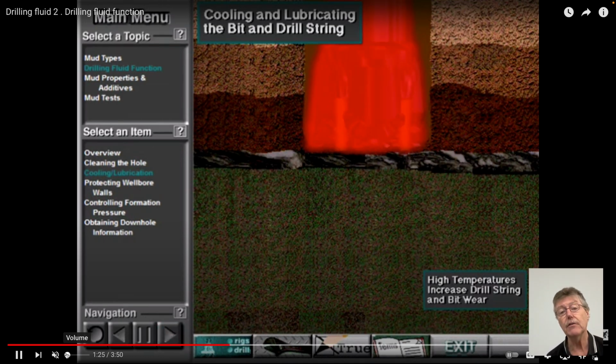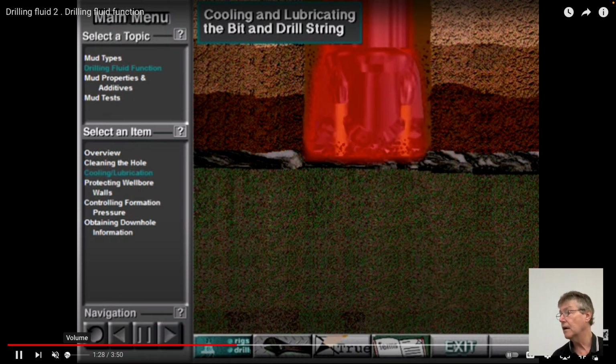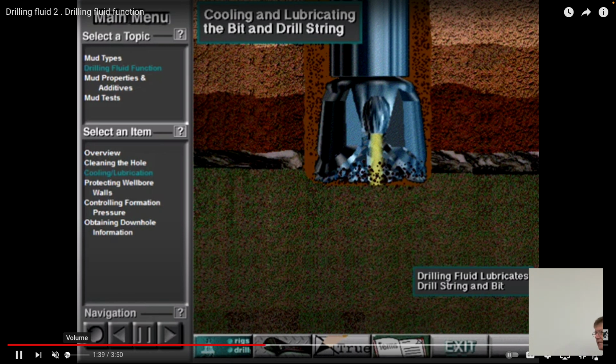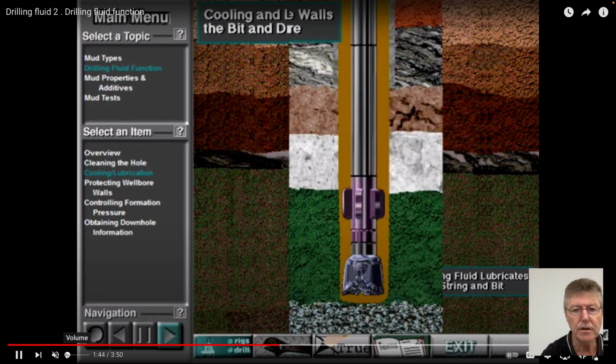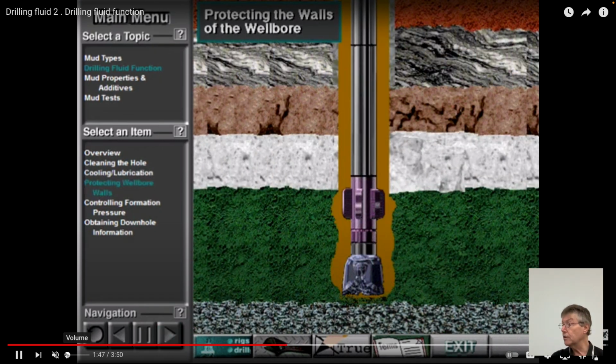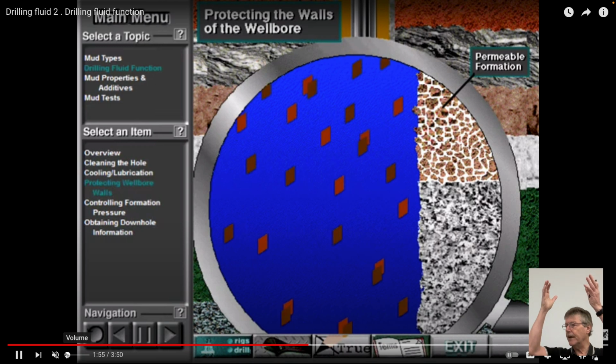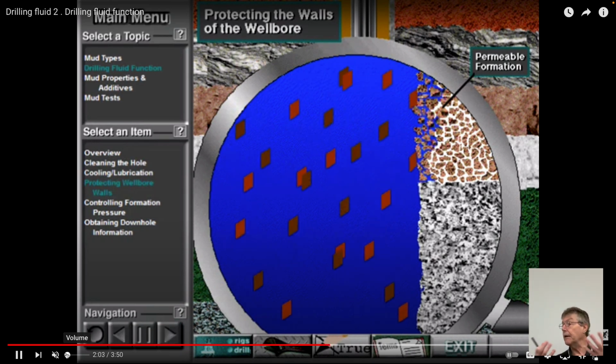But in the drilling, relevant to what we're talking about now, you'll typically use mud. Mud will keep the hole open by applying a pressure against it. It's usually not just water, it's usually mud, which is a mixture of water and bentonite clays in a suspension. That's denser than water, and so it pushes back on the well bore to keep it open as you drill down. It's circulated down the center of the drill string, lubricates and cools the bit, and then comes up on the outside of the drill string in the annulus between the hole wall and the drill string itself. And so it carries up the debris that it drills up.